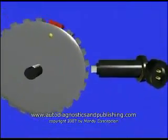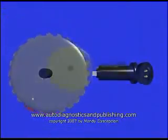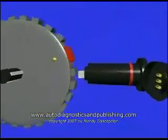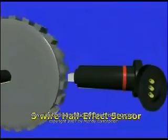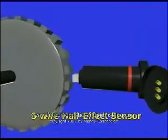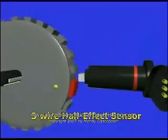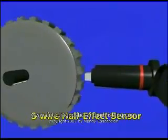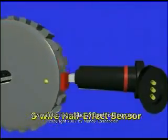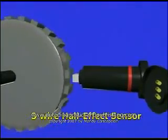Hall effect sensors, which are very common, work by toggling or pulling a reference voltage to ground, thereby creating the square waveform. This reference voltage, to be toggled by the Hall effect speed sensor, is provided either by the ECM or the ignition control module, or ICM. Remember, the output of a Hall effect sensor, magnetoresistive sensor, or optical sensor is always a square wave.